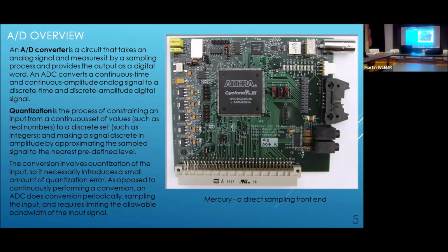Also, what happens if you're sampling at a rate of, for argument's sake, say a 1 nanosecond clock, which is basically a 1 gigahertz sampling rate? And yes, you could buy A to Ds today that'll do that. Empty your wallet, but you could do it. Okay. So what happens if you try to feed that 1.5 gigahertz or something faster? It's going to do what it can.